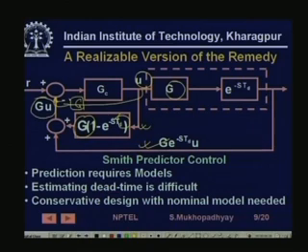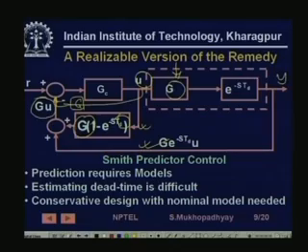But what do we get then? Then we get what is known as open loop control. There is no feedback. What are the problems of open loop control? Any error in G will directly affect the output Y. Any disturbance here will not get corrected. The biggest advantage of feedback control is that it gives you performance generally irrespective of, of course you have to know certain things, but small modeling errors do not affect performance.